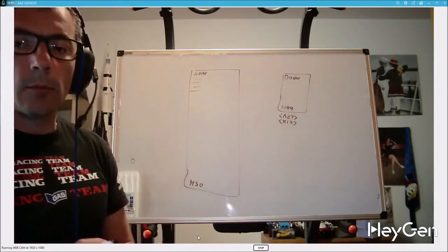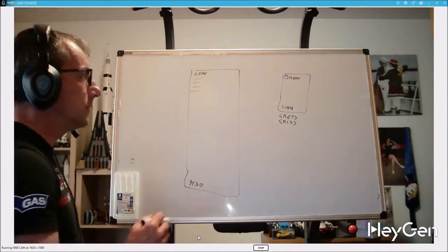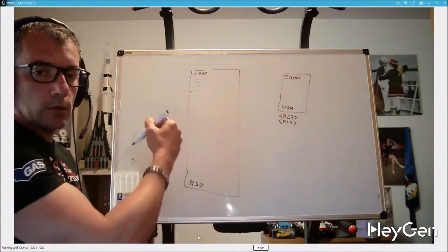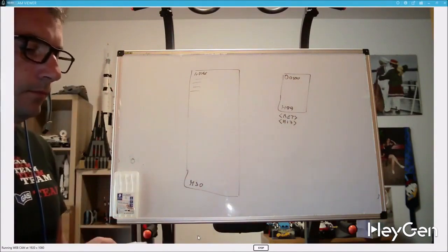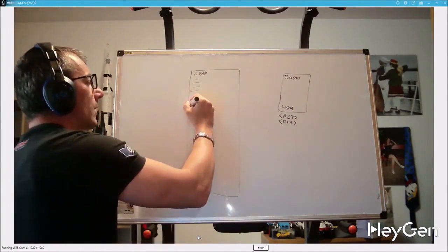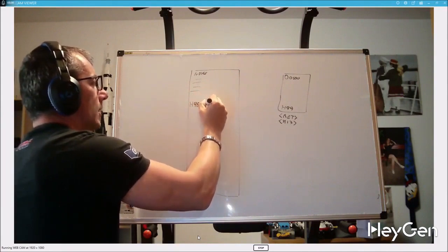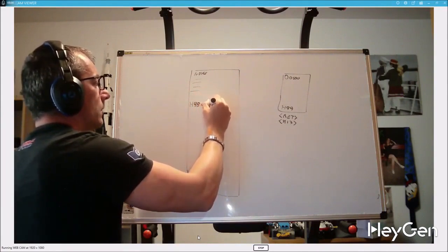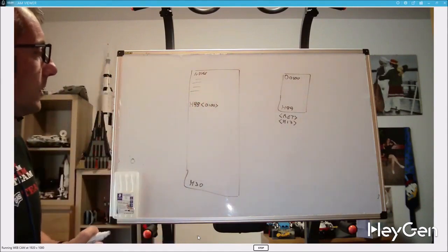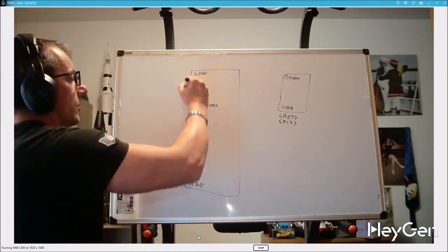a subprogram is an M code or some other special character that says that the code lines are part of a subprogram and that you will have to return to the main program. So, when we call M98 to subprogram 100 within a program, the machine reads the main program, sees this line, then moves into the directory, reads, and since it doesn't encounter an M30, but an M99, it returns to the next line after M98 and continues reading the program.